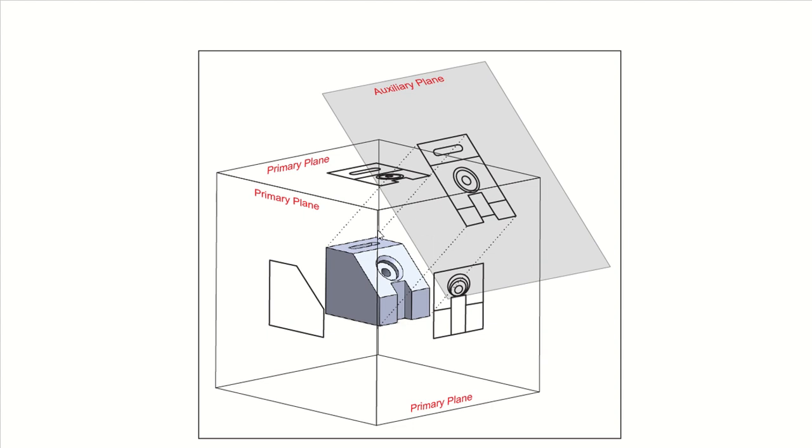And you can see this part. Since we want to show that part, we make a little angle and then project it, so we can see a little bit different. Here, of course, this one is not showing, so this is, I would say, a combination of the top and the right views right in there, because you can see, of course, the dimension is a little bit different because this is longer. See, pay attention. Of course, we can see the top part, all of it, and also the right side part on it, when you angle it. So this is your auxiliary view example.